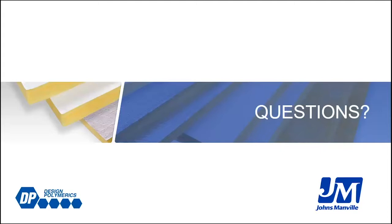So I'll take that one for the duct wrap side. When you join two sections of duct wrap together, you're going to tape that together, and that tape will have the same vapor barrier. Usually it's made of the same FSK facing or PSK facing that your duct insulation is made of. There's a staple flap that comes from the factory that allows you to overlap that joint and put the two pieces together. You'll want to tape that down and squeegee over it. You can also use mastic over top of that if you'd like to, but that's going to provide you with your vapor barrier on a duct wrap project.